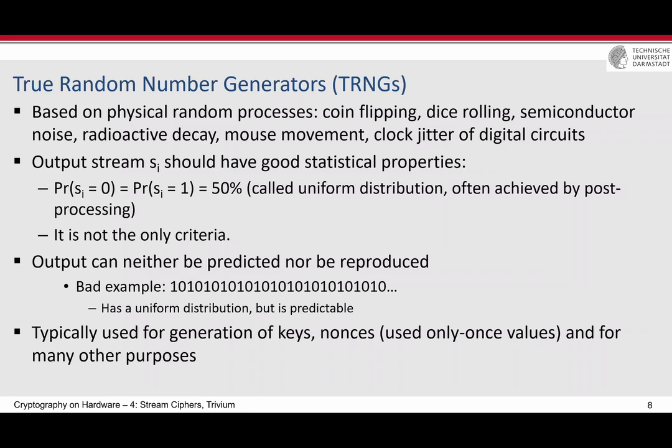I mean, I could just use the TRNG. But this is the point: the TRNG is slow. You generate the seed after power up, and then with a very high speed, you can generate a random stream with the PRNG.